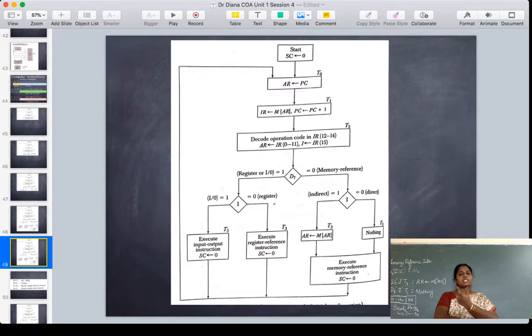This nothing phase is used for synchronization between direct and indirect memory access instructions. So from time cycle T4 onwards, whether it is direct or indirect memory access, I can use the address register itself for receiving the data. So this is what we have seen earlier.